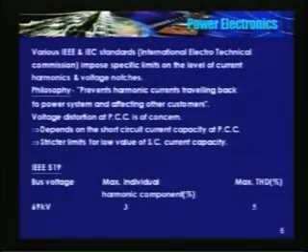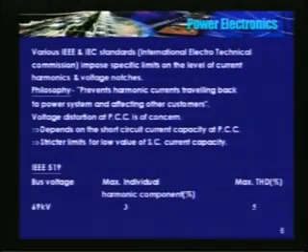Basically, power quality and the harmonic content limits of various standards is a subject by itself. I will just give an example: similar to IS Indian standards, there is IEEE 519. What it says is if the bus level is 69 kV, the maximum individual harmonic content should be less than 3% and the maximum total harmonic distortion is 5%.